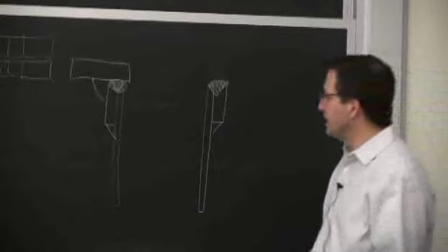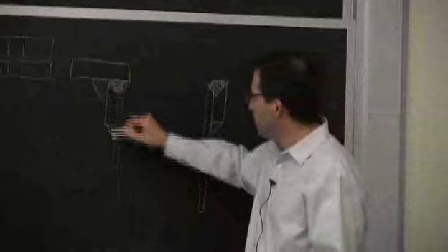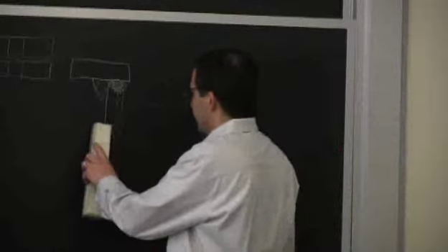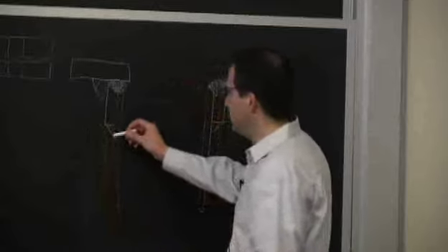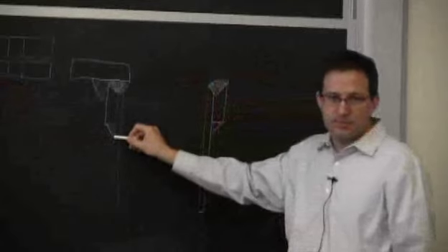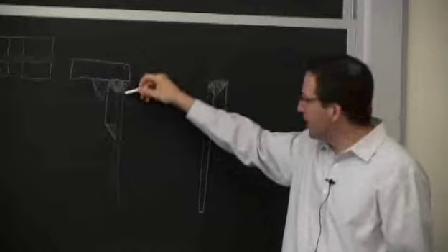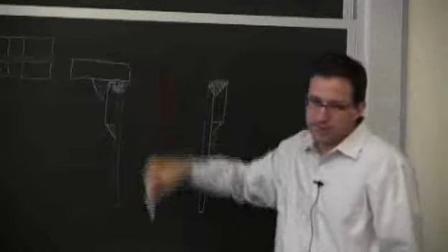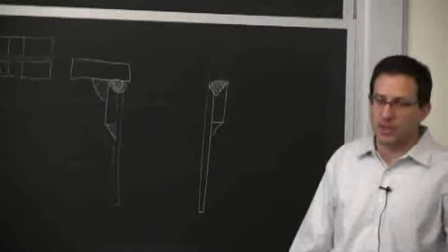So I'm using this as an example on how to move away the highest stress in the weld. So it used to be up here. Now we moved it down a little bit. We have much less bending load on that pipe, and we created essentially a stronger section up above.